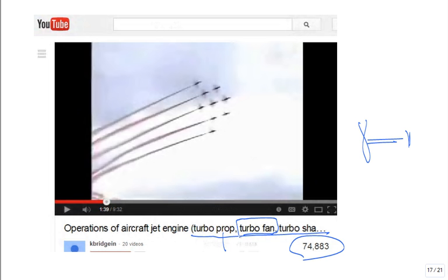Turbofans are very, very common. And so what you do there, I'll just give you a quick overview, is all of the air doesn't go through the compressor and then bypass and then go through the turbine. They'll have a big fan on the front, and it'll take a bunch of air and bypass the whole thing, but it'll be mixed. But that fan is being driven by shaft power coming back up by the gas turbine. And what engineers found is that it's efficient to take some shaft power, bring it up, and have a fan to really ingest and propel backward a lot of air. Also, that air then helps quiet that engine.